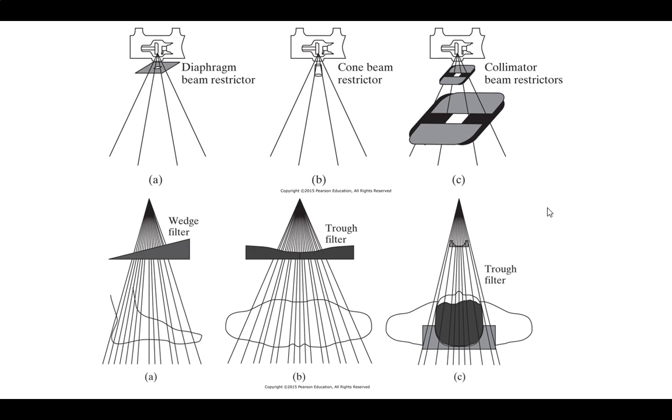Most of these things are designed so that you can have them regularly tested and replaced as part of the maintenance structure. The filter is generally pretty cheap, and you're going to replace it anyway, so if I put the attachment points outside of it, it simplifies my replacement scheme for maintenance.